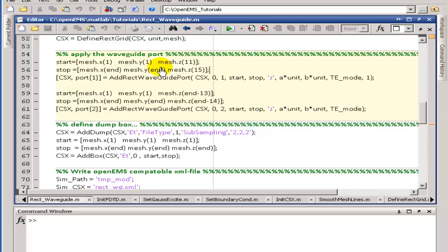Here we have something to talk about. As we have PML in the Z direction, we have to be far enough from these PML layers. On the other hand, the mesh size in the Z direction, which is the direction of power transfer, needs at least 2 mesh cells to represent your port.